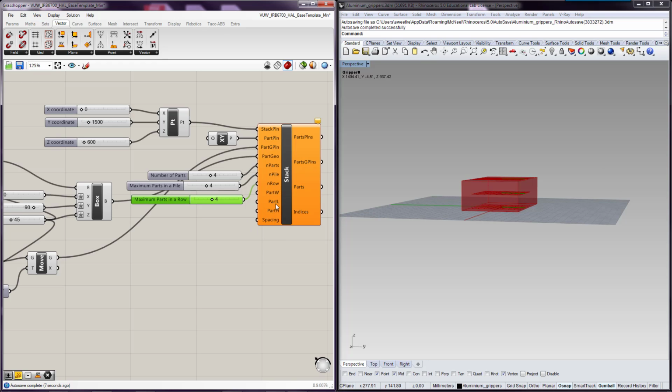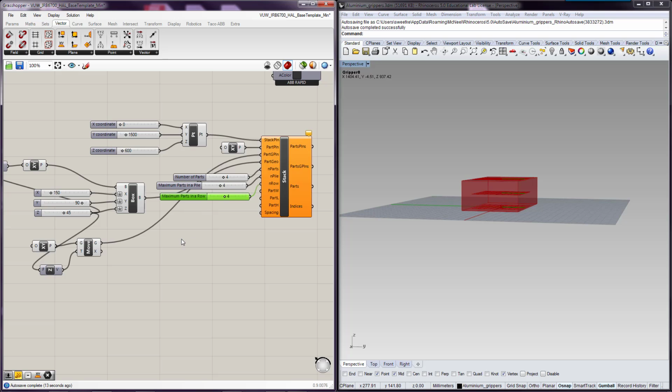So we need part width, length, and height. Essentially, this is getting a bounding box, but because we are using a box, we already have all of these, so we can feed our same values here: width, length, height. All right, and the spacing is the spacing between the blocks. So we found that somewhere around 80 is ideal, clears the grippers, and I can feed that in there.